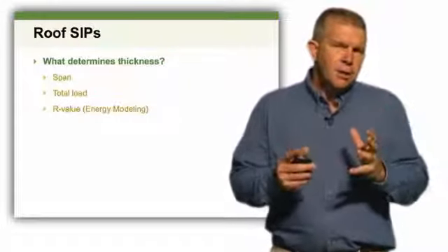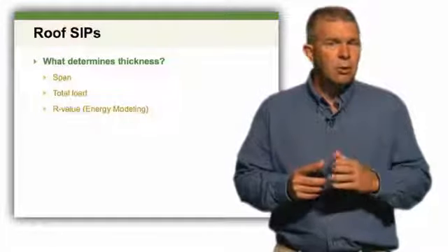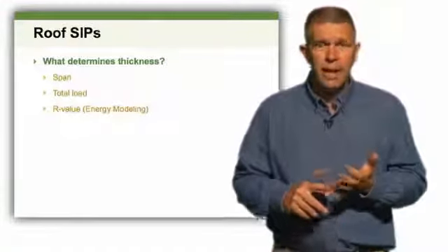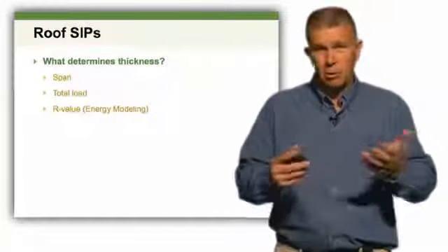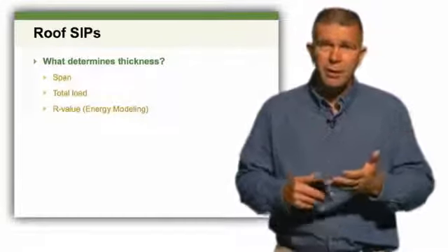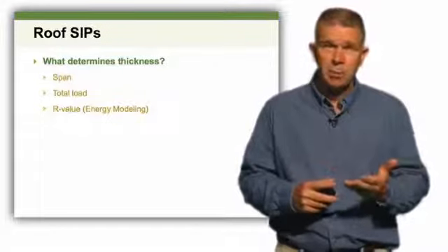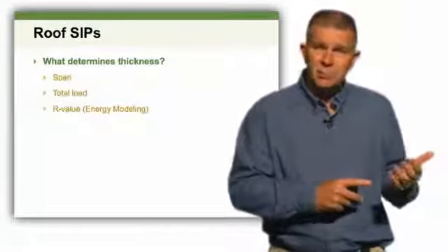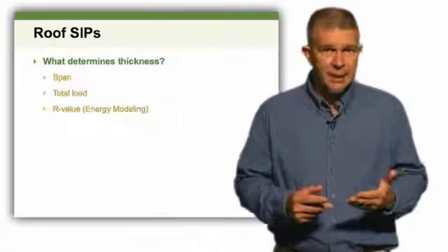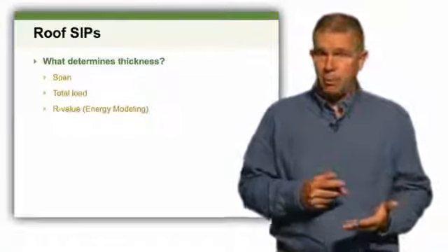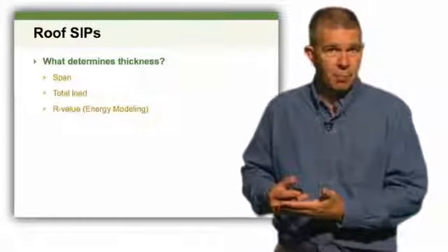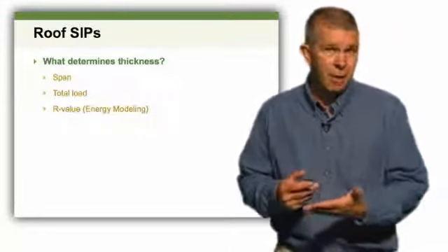But the thickness of the panel most often should be determined based on what our total load on that roof is and how far it is going to span. So we need to look at the roof support structure and make that determination of how thick that panel is going to be. And then, of course, we need to go back to the beginning of this module, where we talked about the different connection details and whether or not we were capable of using a surface spline connection, or did we have to start putting lumber inside of our roof panels to help meet that span requirement.